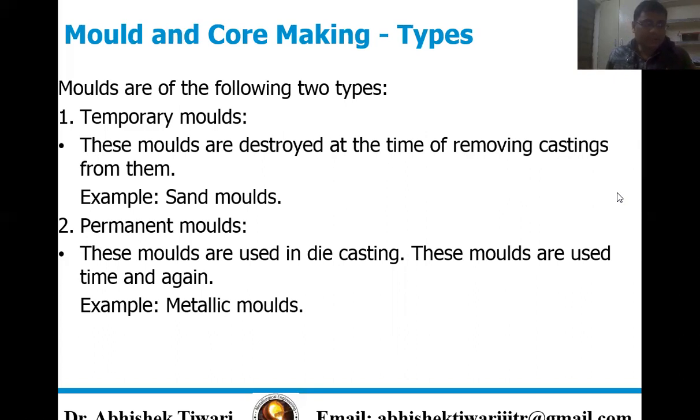In a skin-dried mold, the advantage of a dry sand mold is partially achieved by drying the surface of a green sand mold to a depth of 10 to 25 mm at the mold cavity surface using torches, heating lamps, or other means. A special bonding material must be added to the sand mixture to strengthen the cavity surface.